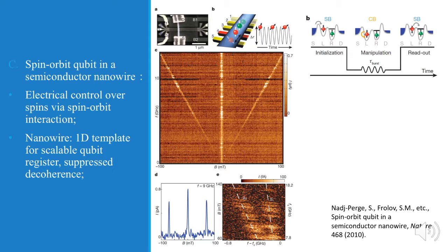So if we look at figure B on the left, we can see that a microwave frequency electric field applied to gate 4 oscillates electrons inside a nanowell. This motion can induce resonance transition between spin-orbit states by means of EDSR, which I talked about in the previous slides. At a resonance, the spin-orbit state of the double dot rapidly changes from parallel to anti-parallel. So if we look at the figure B on the right, we can see this transition. So the anti-parallel state cannot experience spin blockade, so the left-hand electron tunnels to the right, thereby contributing to a